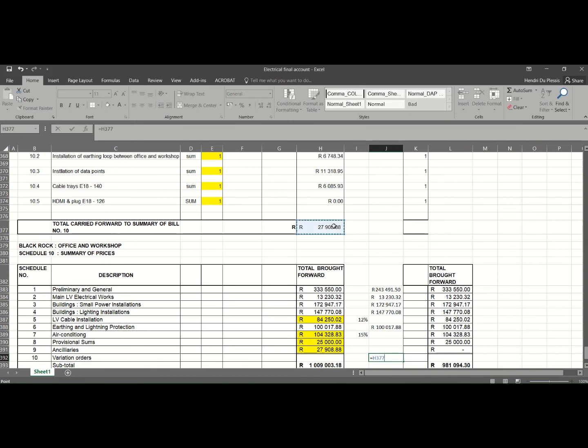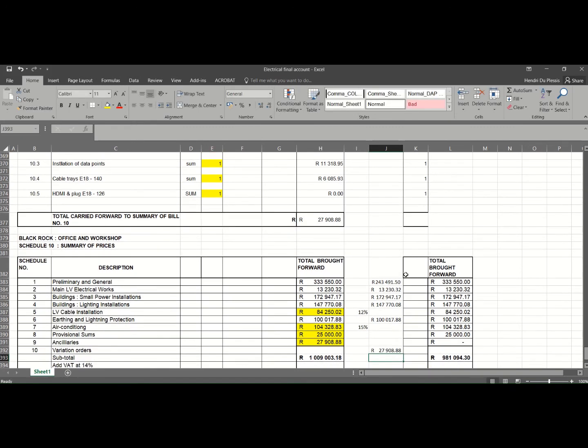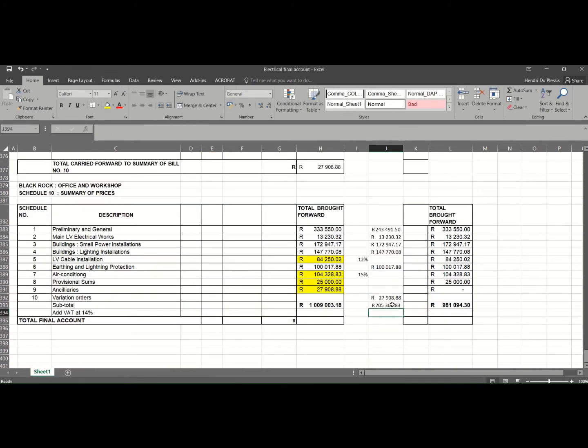Okay, in your case, variation orders probably won't be included. So then we do our sum. Okay, so we get to our new rate, and for this building it was more or less 100, and it's two buildings of 117, or 70 times 2, so we had a construction rate of 2,000 Rand per square meter.